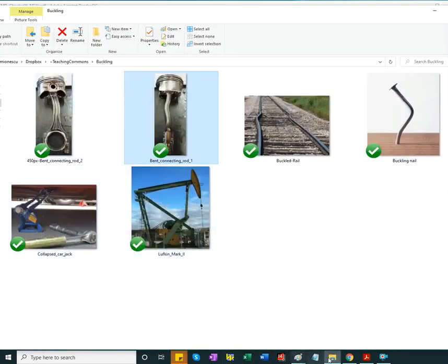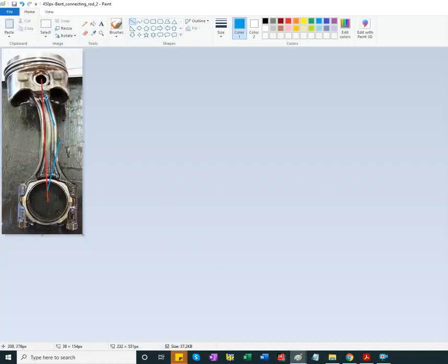The other example we had, and sizes are different, so here the geometrical stiffness is more because of the pin and the connecting rod allowing for rotation. So this will be more prone to buckling for a round cross section, more prone to buckling in the transverse plane than longitudinal plane.